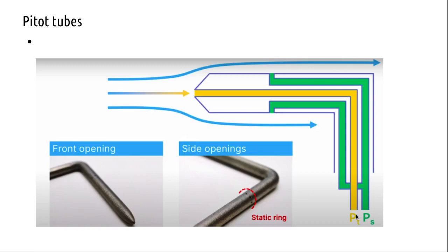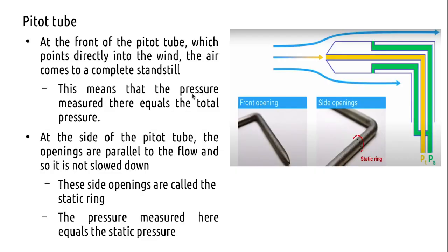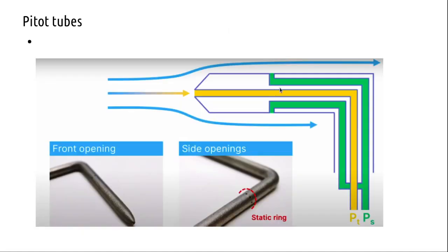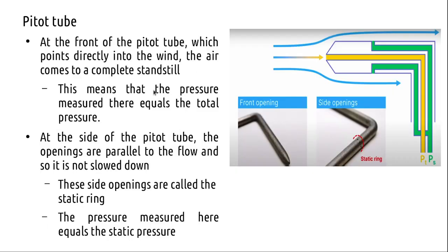Any type of pressure transducer could be there. You could have a piezoelectric transducer maybe, so that the pressure is converted to an equivalent electrical signal. So that is measured there, and this is the total pressure that is measured. That is the front point is the total pressure.